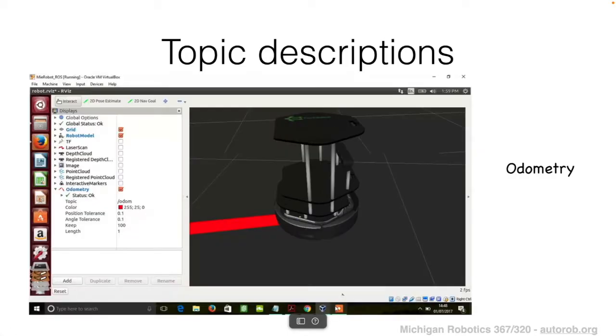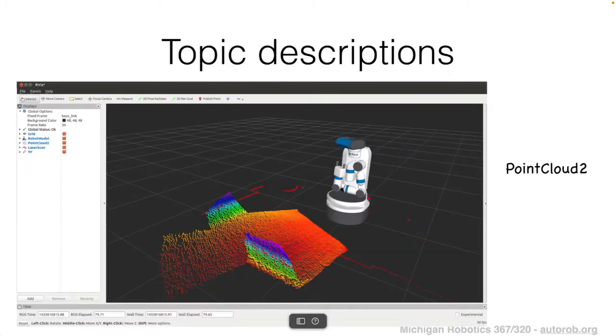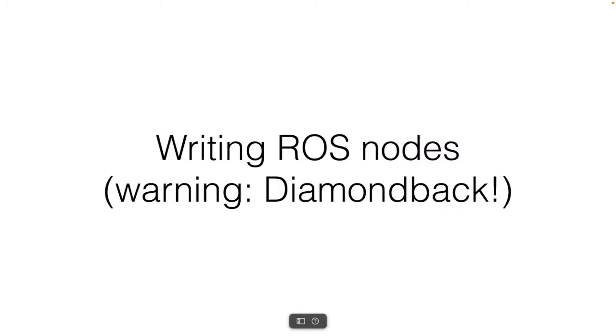And then in addition, there's a few more. If you're curious about any of these specific ones, feel free to look through the ROS documentation, or we can discuss it during an interactive session. But there are also data types specific to, for example, odometry and also point cloud data. Point cloud data we see very frequently in mobile manipulation robots. For example, the Fetch has a built-in point cloud sensor, and ROS can support all of these different data types using unique message data structures for them.